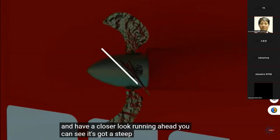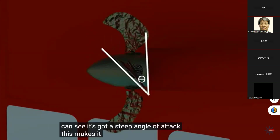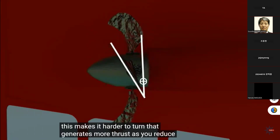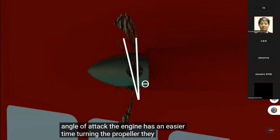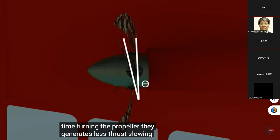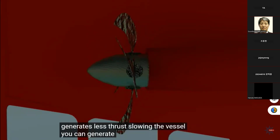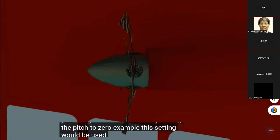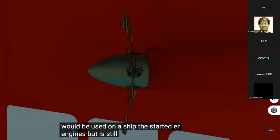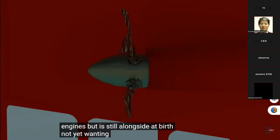Running ahead, you can see it's got a steep angle of attack. This makes it harder to turn, but generates more thrust. As you reduce the angle of attack, the engine has an easier time turning the propeller, but it generates less thrust, slowing the vessel. You can generate zero thrust by setting the pitch to zero. For example, this setting would be used when a ship has started her engines but is still alongside her berth, not yet wanting to move.